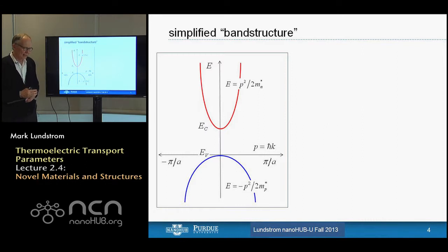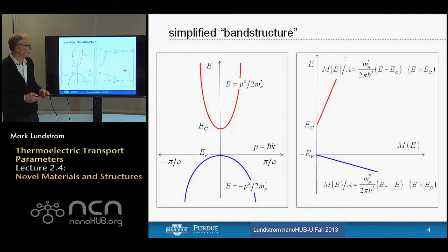So we've been thinking so far in terms of very simple band structures. We have very simple relations if we look at the energy versus k plot, or ħk, crystal momentum. We've been taking very simple descriptions of energy versus momentum for electrons or holes in terms of an electron effective mass or a hole effective mass. If the band structure is simple, then very near the bottom of the conduction band or top of the valence band, this is not too bad. And we've seen that under these conditions, we can simply derive the number of channels in the band.